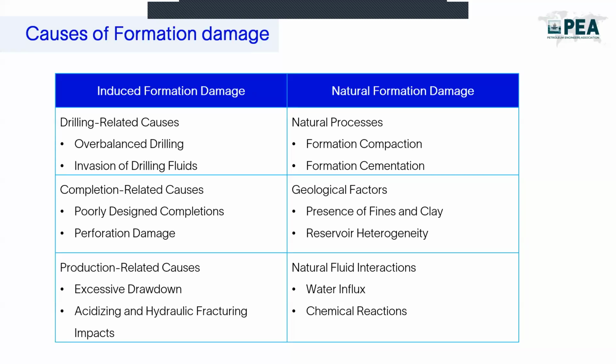The other thing is invasion of drilling fluids. The penetration of drilling fluids into the reservoir rock leads to formation damage by introducing fine particles and chemicals that block the pore spaces and eventually alter the rock properties. So I would like to tell you about a case that I've been through.